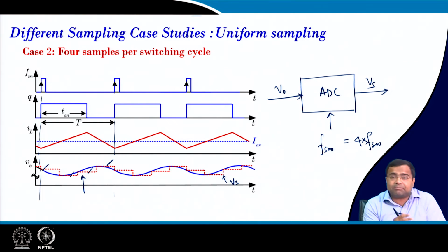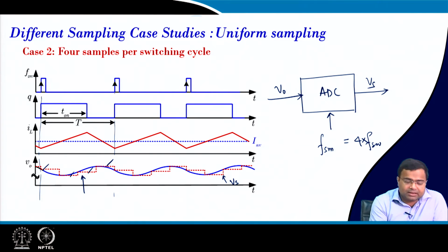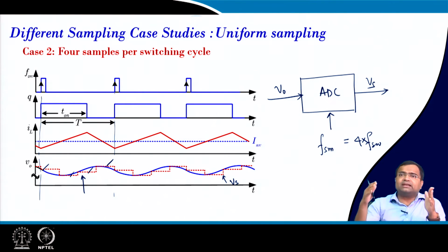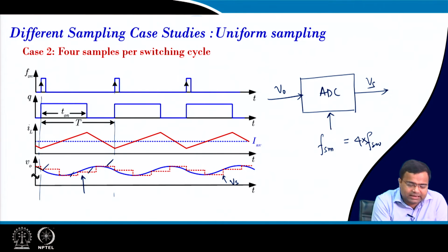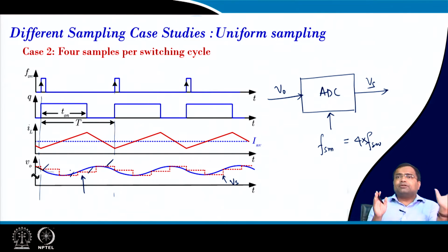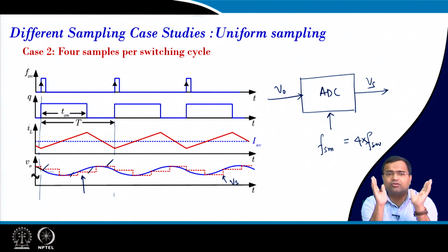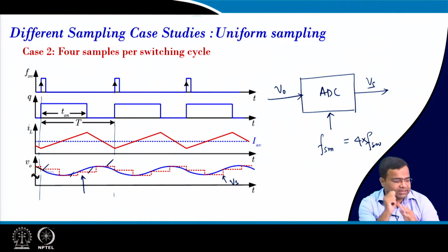But generally with multi-sample, since you are taking more samples, naturally the voltage update rate is high, so you can reduce the delay. That means multi-sampling can be helpful to reduce loop delay, but at the cost of more power and processing. There are many research papers on how to interpolate the intermediate information, because you are not getting the information between this point and this point, so you can interpolate. We are not going into detail, we are just throwing this out so that you can think about whether it is possible to use 4 or 5, which we will discuss when we consider the MATLAB case study.